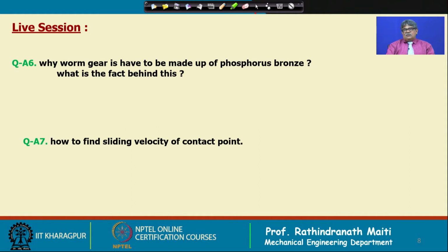Okay. So, this angle becomes such that if you consider the helix angle of the pinion, that will be 90 degrees minus the pitch angle, which is very high. And for that much inclination, there will be too much sliding motion. That is why the efficiency of the worm gear is less. The efficiency of the worm gear is very less.